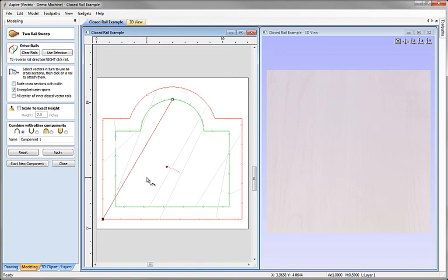Now I could go out and adjust that on the vector itself, or we also have the option in here. If I come over this point, you'll see I get a little crosshair shown to me on the cursor with a little check mark, and I could right mouse click there and then choose the option to make start point. So if I click on that, we can see that's moved my start point to the adjacent corner there.